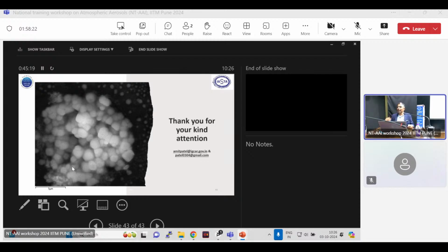When you are sampling the aerosol, these are metallic aerosols, and again they are health hazardous. So whatever instrument you are sampling with, after your instrument there should be a zero filter. And where you are doing sampling, the room should be well ventilated, and all systems after the instrument should have the zero filter. So these are the few health precautions I can recommend. These are the precautions we need to take care of.